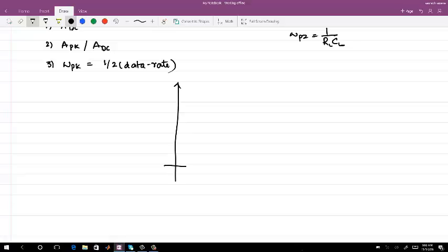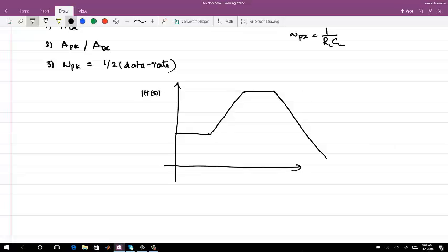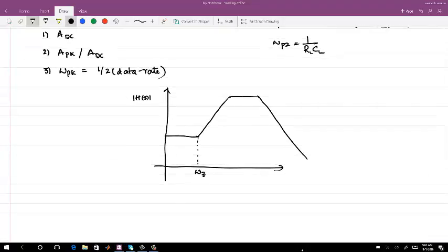Okay, so I know what my DC gain should be, I know my peaking frequency, and it will be because of the second pole. This is just a Bode plot in logarithmic scale, mod of H of S. Now, the thing which I know is omega Z. If I pick a certain omega Z, what happens?